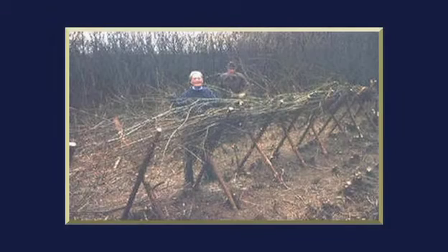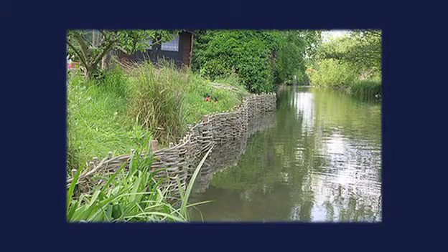Wattles and fascines are used in the permanently wetted zone. Wattles consist of a row of stakes hammered into the ground. The stakes are braided with flexible, strong brushwood. Fascine sausages are cylindrical bundles of willow rows with diameters of 10 to 15 centimeters, used for stream bank protection and bank stabilization. They are manufactured with flexible brushwood and anchored with stakes of about 1 meter length.